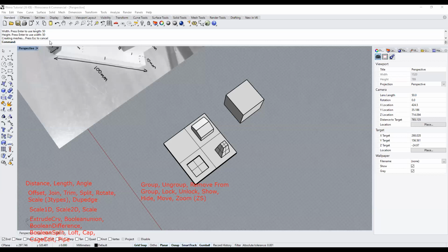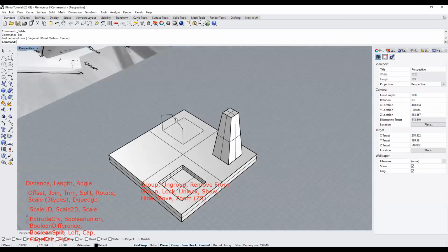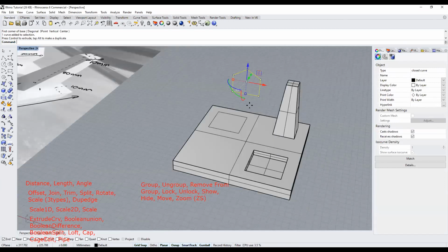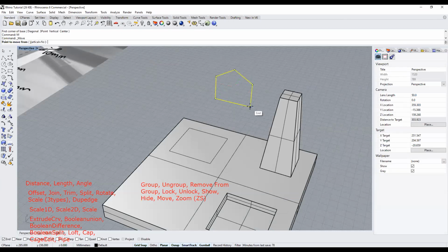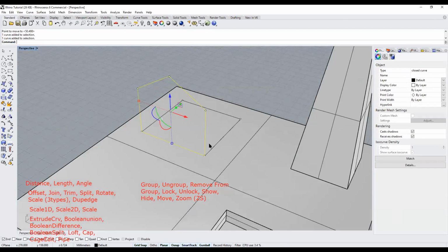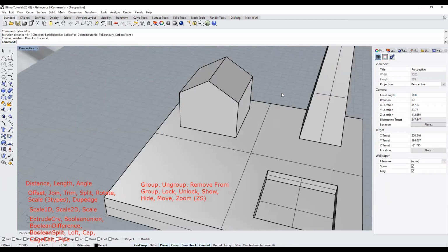How do you snap the cross section of the house into its spot it's meant to sit? A lot of the time why you use curves is because you use them as a sort of guiding tool. So I basically just type move, make sure my cursor is on the end, and the end tab pops up. You click onto that corner and I snap it on this corner. So this is basically like a ruler for me. I want to know exactly how much I extrude it. So when I extrude this curve, I click onto the point I want to end and it's done.